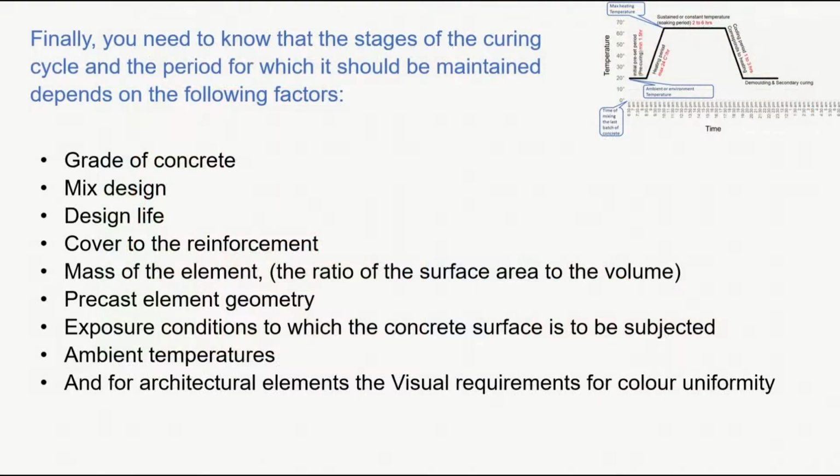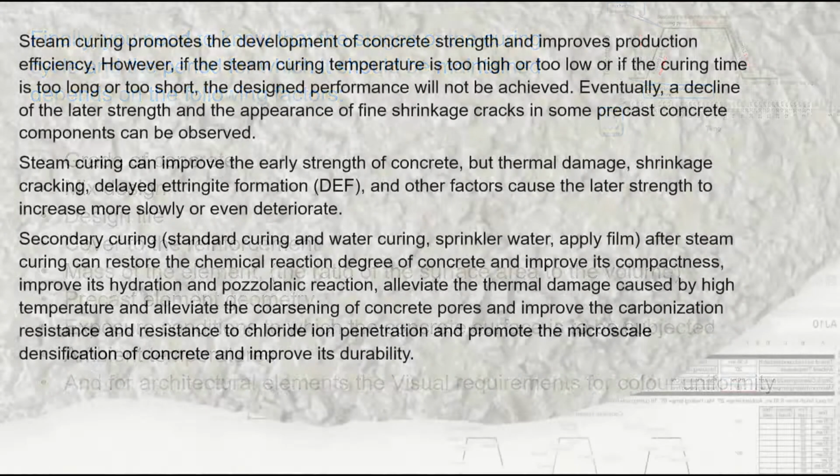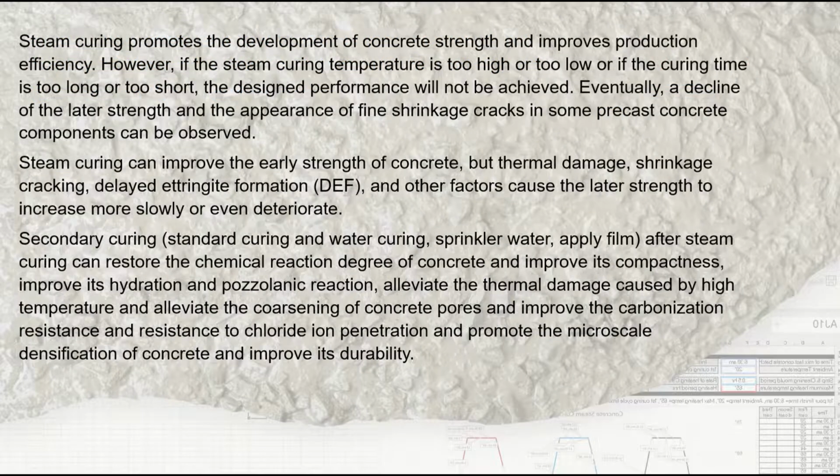Finally, you need to know that the stages of the curing cycle and the period for which it should be maintained depend on the following factors: grade of concrete, mix design, design life, cover to the reinforcement, mass of the element, precast element geometry, exposure conditions to which the concrete surface is to be subjected, ambient temperature, and for architectural elements, the visual requirements.